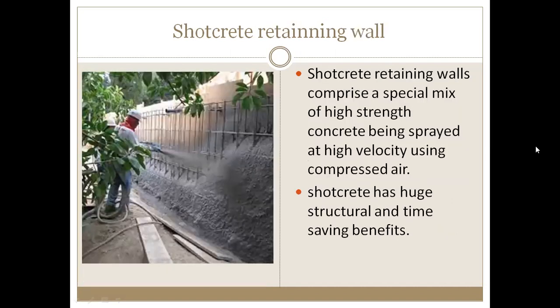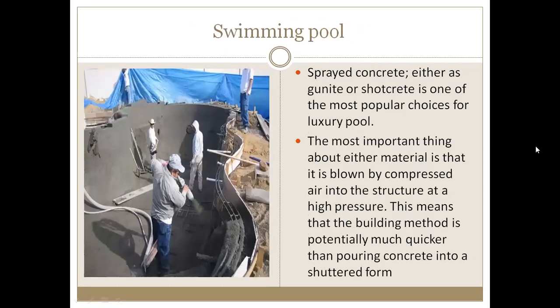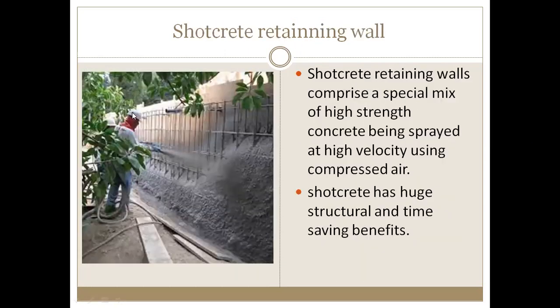Shotcrete retaining walls. Shotcrete retaining walls comprise a special mix of high-strength concrete being sprayed at high velocity using compressed air. Shotcrete has huge structural and time-saving benefits. You can see in this picture the man is using sprayed concrete in the retaining walls.